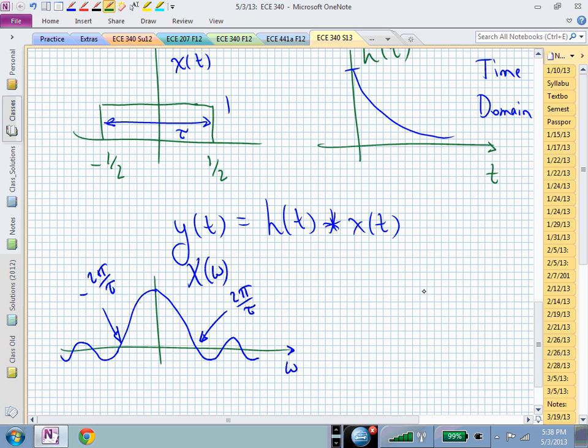That now tells you a little bit more about what's happening in terms of the frequency content of your input. If you now wanted to say, well, how is that going to be impacted by my system? Now it might be nice to know what the frequency response of H of j omega is. If it was this exponentially damped system, then maybe it looks like this.